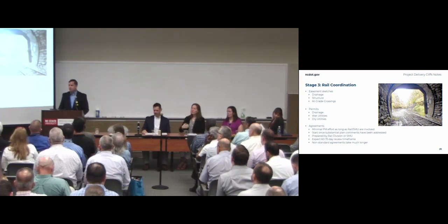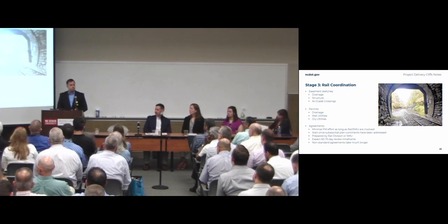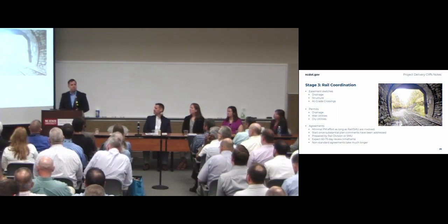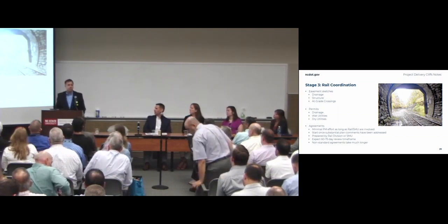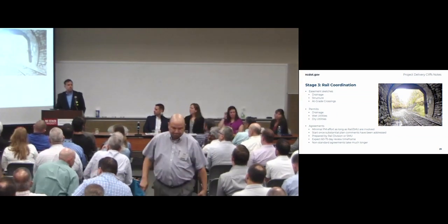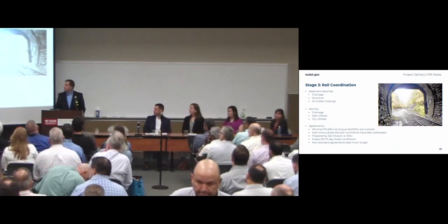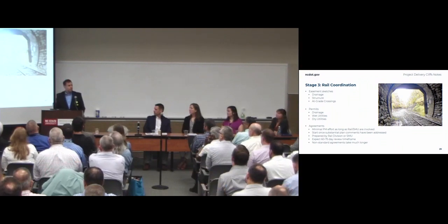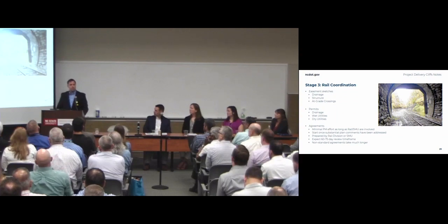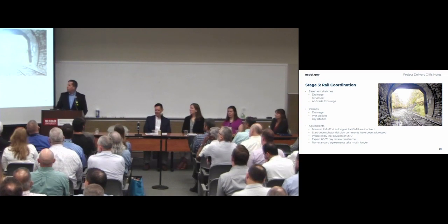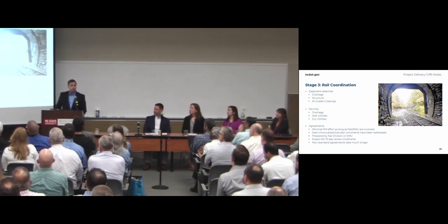What these identify are temporary easements for construction, permanent easements, whether it's an at-grade crossing or a grade separation that has interior bents, and aerial easements for overhead grade separations. These are not shown on the plans, so that's still the same way as we've always done in the past. These are just completely separate documents that are recorded by the railroad. This occurs basically once all plan comments have been addressed, so typically shortly thereafter the project agreement has been developed and is underway.